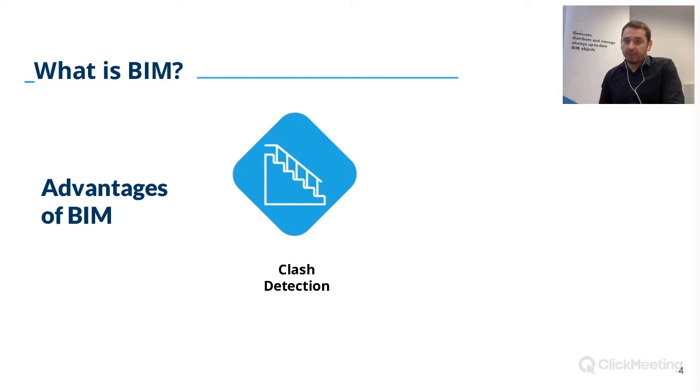This different way, I'm referring to BIM of course, focused on several aspects which the typical way of doing design was not able to address. First of all, the idea was to be able to do clash detection. When doing the design, we should be able to detect potential conflicts as early as possible in order to address them sooner. If we, for instance, prepare the lift shaft and it is in conflict with our piping or air conditioning system, we should be able to detect that at the design phase rather than at construction time. BIM allows us to do that, because instead of working with very abstract things like lines, the designers start dealing with something more tangible, more concrete: walls, slopes, beams, lift shafts, windows, and so on.